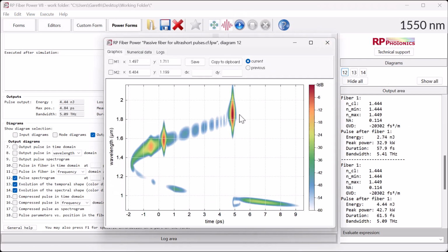Now, we observe significant spectral content below the zero dispersion wavelength, entering the normal dispersion range. The output also has a roughly parabolic shape. This is because different spectral components have different group velocities, with the zero dispersion wavelength having the highest. We also see some blobs, indicating soliton pulses. These are separated enough so that they propagate as more or less independent pulses.